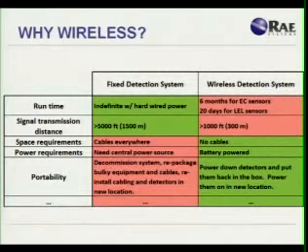Again, you have the power requirements. Wireless gas detectors are battery powered. And then we talked a little bit about the portability. Especially in oil and gas exploration, we know that the rigs move around frequently. So if you want to install a fixed system, you can, but then when you want to move it to the next drilling location, you've got to pack up that system, make sure everything's safe, and redeploy it at the next location, which can take anywhere from a few hours to a few days when you're talking about a fixed system. With a wireless system, you literally take the detectors off the wall, put them in the box, bring them to the new location, turn them back on, and you're ready to go again. It's literally minutes versus hours or days.